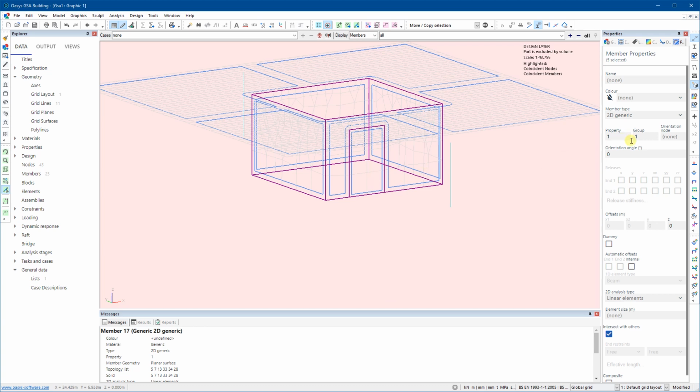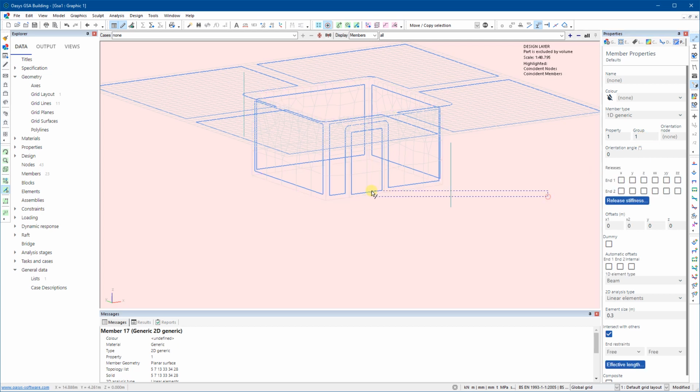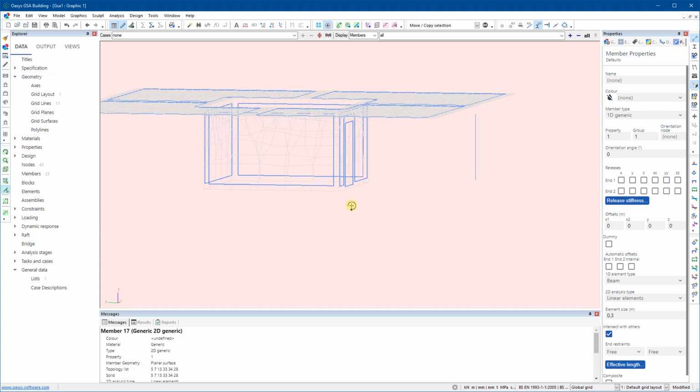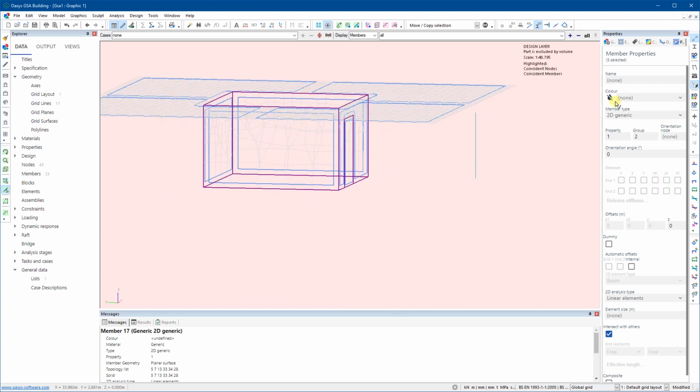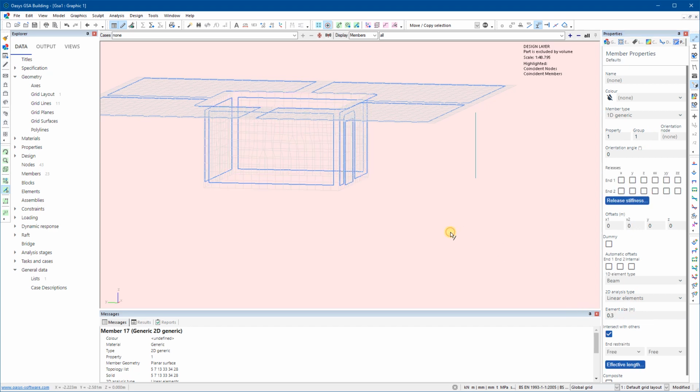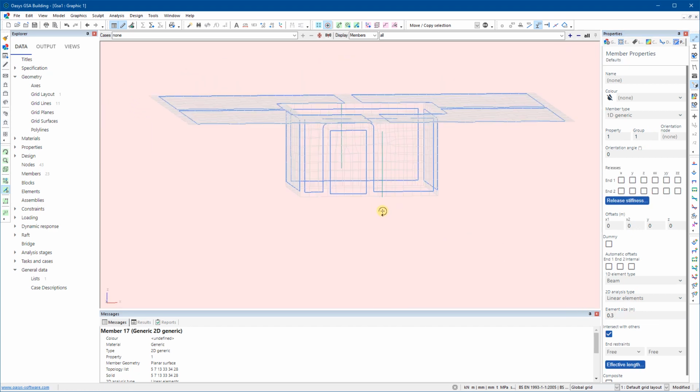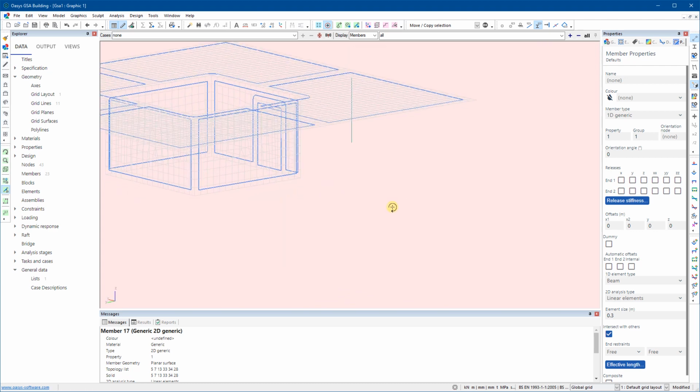So the first thing I'm going to do is change the walls to group 2. So again, I can define those in a list later. So group 2. And I'm also going to set the element size. And again, I'll just choose to set it to 0.3. And again, you can see the mesh has been refined.